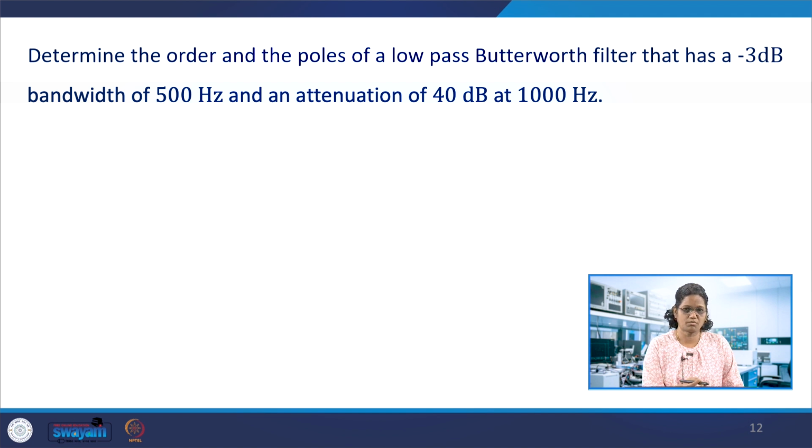The bilinear transform would be better than impulse invariant. Once discretized, we get the coefficients and develop the Verilog module, as we had seen in one of the examples of how to write it. Once we have these coefficients, B naught and A naught, that is the feed forward and feedback coefficients, the Verilog module can be developed.